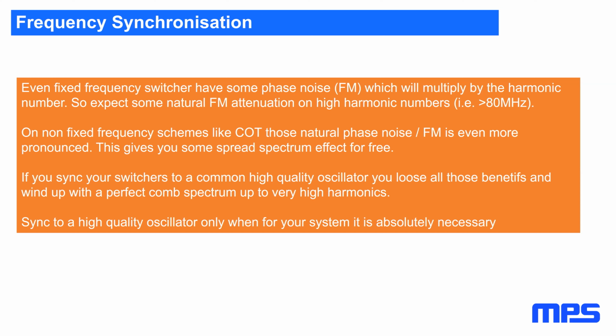If you now force this switching regulator with an external high quality, high Q crystal, it very easily can be that something which passes EMI with the internal, noisy oscillator, since you have it set really close with a high quality oscillator, all of a sudden violates your EMI goals. So don't be surprised if stiff synchronization makes matters worse.